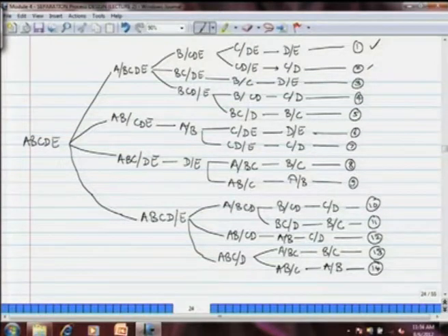Then the second sequence is the ABCD mixture, A taken off first from BCD, then the BCD mixture split in half, BC together being recovered at the top, D recovered at the bottom, and then these binary mixtures are further split as BC and DE. Then in the third possible sequence we have separation of A again from the BCD mixture first, and then the BCDE quaternary mixture is split as BCD together and E being separated, that is an indirect sequence, and then we are left with a BCD ternary mixture which is again split in direct and indirect sequence, like B being separated from C and D and C and D being split in the 4th column, or BC being separated from D and the binary mixture BC split in another column. So, in this way if you start writing, you can write 14 different sequences as shown in this figure.